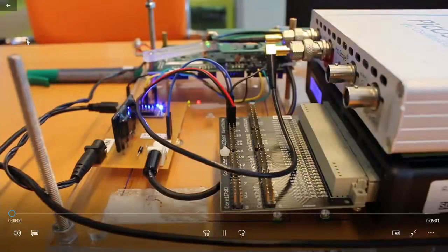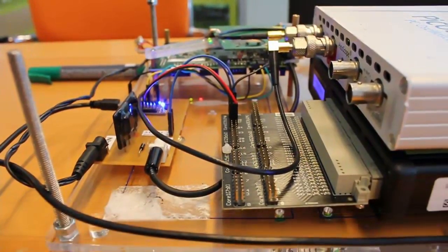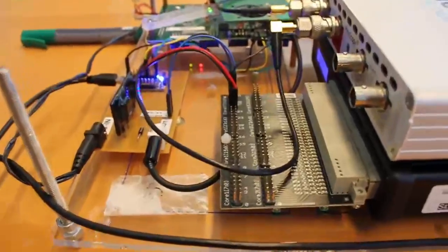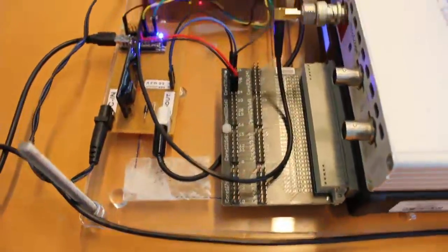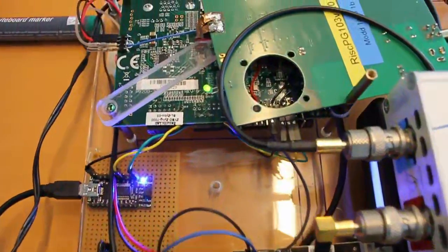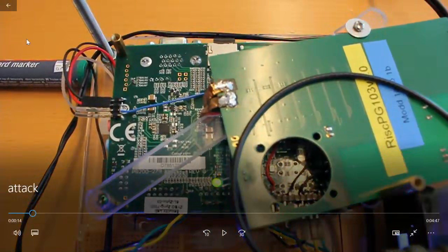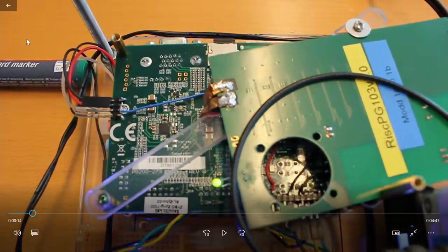Well, at least this time we don't have to worry about the demo not working. This video shows the setup that we usually bring along. Unfortunately, we don't have it this time. As you can see, it's the same setup as I showed before, but a bit more neat. The important part is that this is the actual target where we inject the glitches, and we solder our glitching equipment directly on the PCB because you want to keep the cables as short as possible.